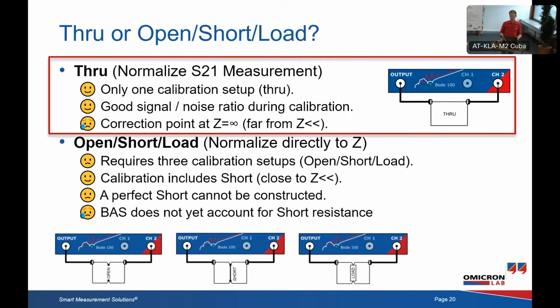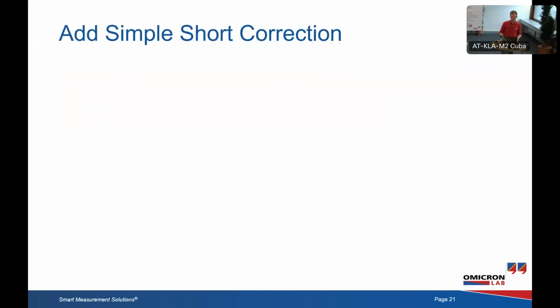So I choose to go with the through calibration because of the disadvantages of the open, short, load calibration. And to improve that a little bit further, there is a simple short correction that you can apply.